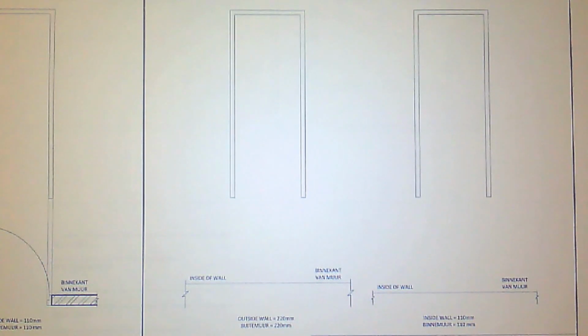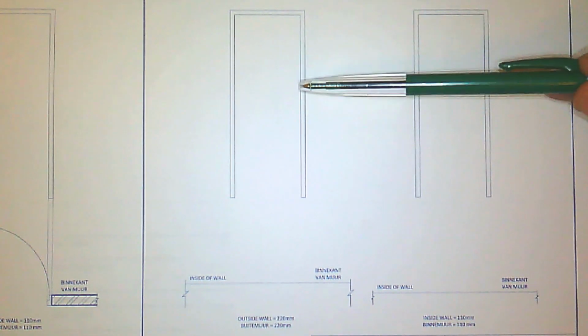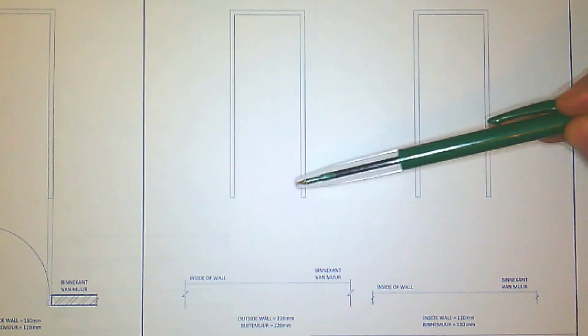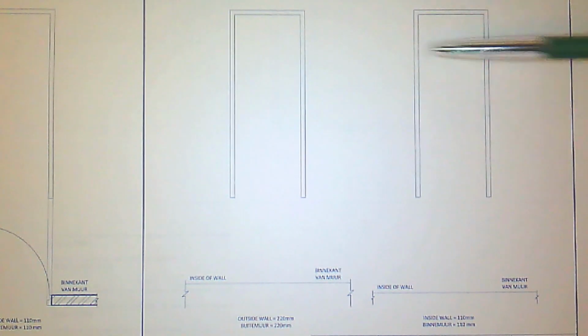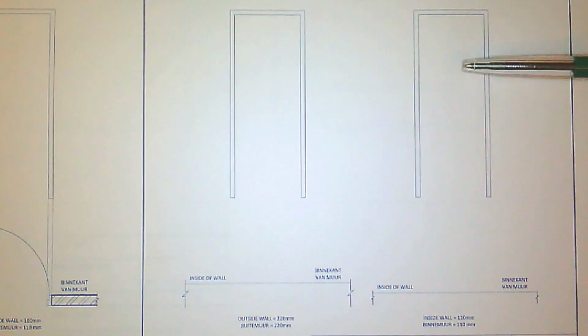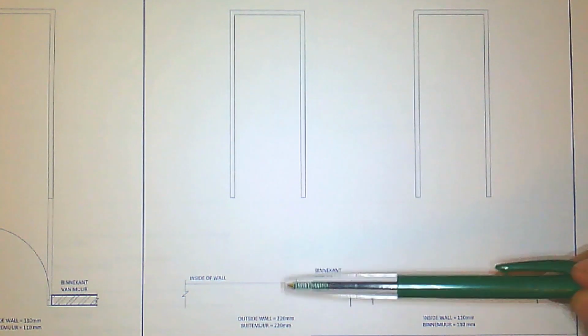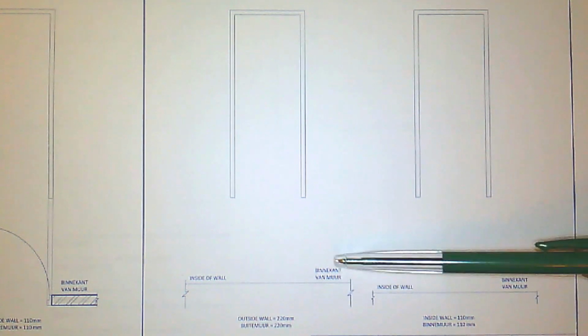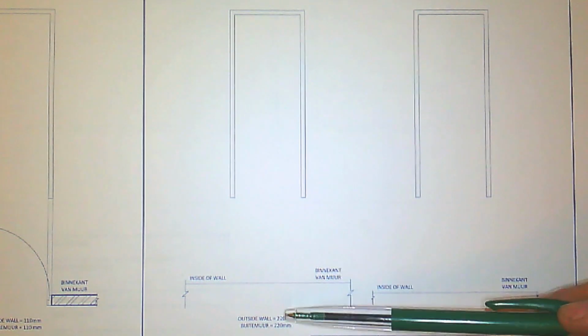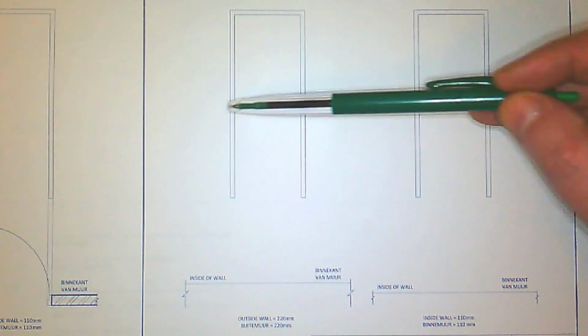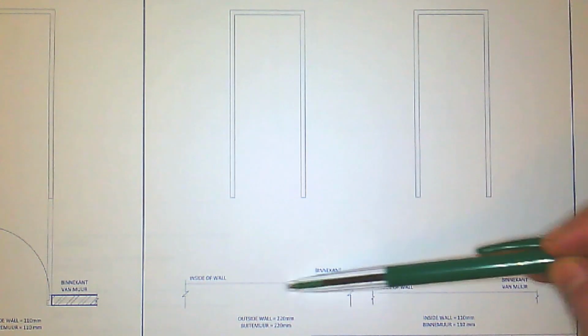Right, grade 10s, the next exercise, they give us the front views of the doorway, and again there's the frame going around, so this would be the equivalent of, let's say, seeing it on a sectional view or a view that's been cut open. And here we can see the top views of the walls. Okay, so this is obviously the inside of the wall, and that's the outside. And they want us to draw this door symbolically in the top views.